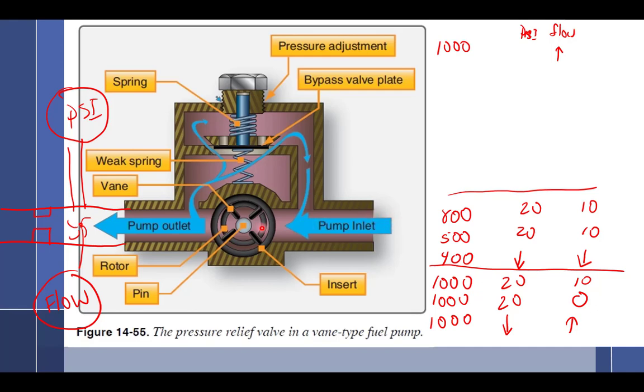And it just comes through here, goes through the pump, comes around, and just sits here. Except I've seen some of the pumps you guys build that leak pretty bad, so whatever's leaking would come in. Yeah. So to put it simply, you could say that it's directly varied when the pressure adjustment is changed, and it's indirectly varied when the orifice has changed. I like that.